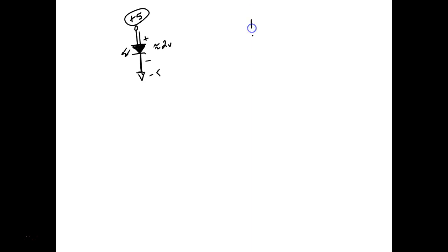So what we have to do is come in here and put in a resistor somewhere within this. We can either come in and put a resistor right here and then connect this to plus 5 volts, or we could come up here and put the resistor right here. It's got to be in series somewhere, right, guys? Then we can put this directly to common and put the plus 5 volts there. So we've got two options.